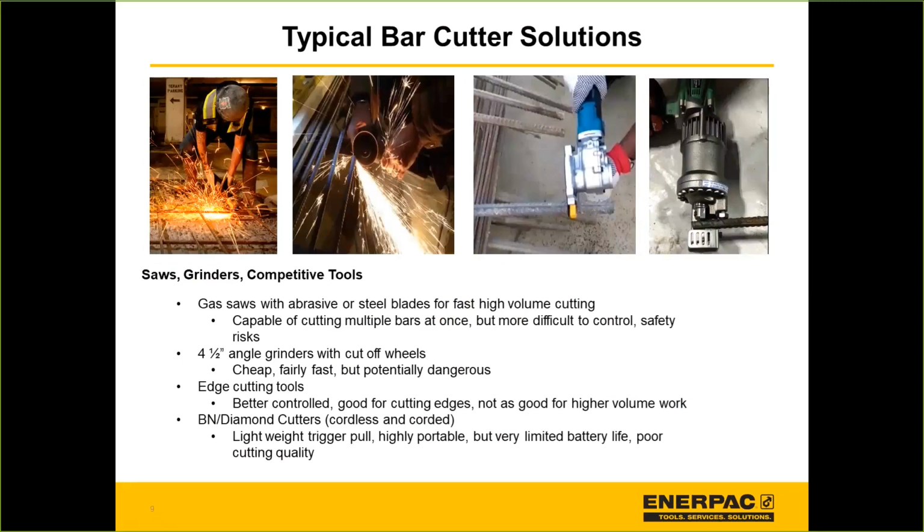There are other solutions out there in the market which are less common, but which are somewhat better suited. One of those solutions is an edge cutter. You see that tool with a blue handle, third picture from the right. Edge cutters are a bit better than an angle grinder for cutting rebar. They're safer. They've got a nice cover.